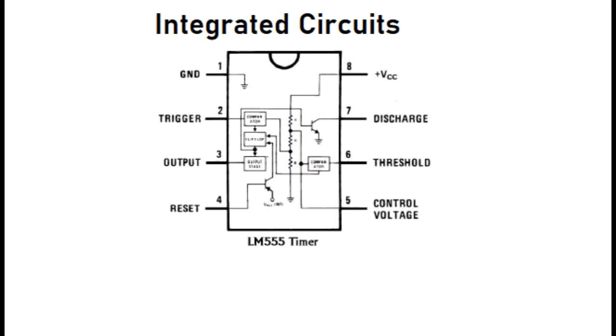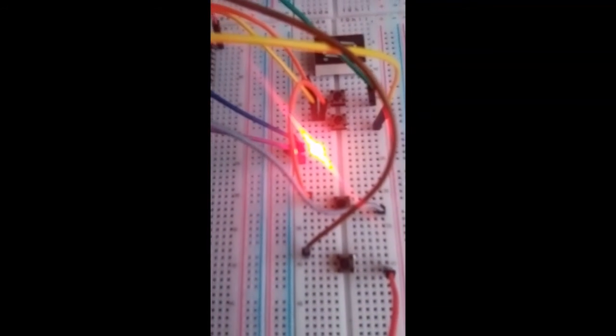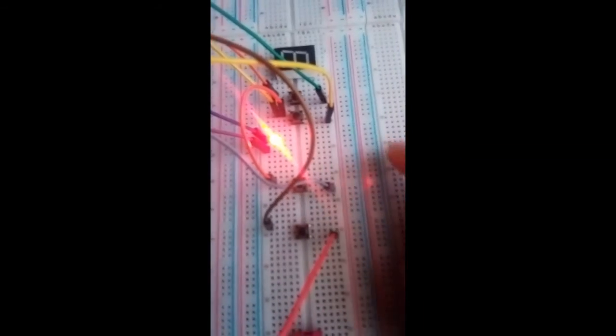This following integrated circuit will demonstrate a flip-flop, and we need a clock, which is this 555 timer, which has an LED that will show you if the clock is high or low. Our output Q has this LED to represent the current state. And here we have 4 switches. 2 of them will be to set our value of D, and then the preset and clear are the top and bottom.